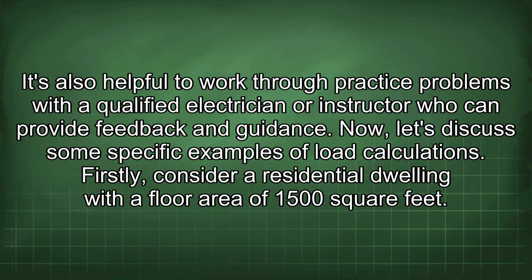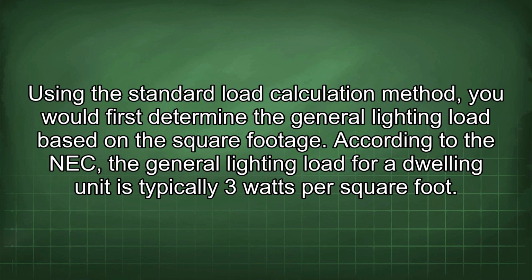Now, let's discuss some specific examples of load calculations. Firstly, consider a residential dwelling with a floor area of 1,500 square feet. Using the standard load calculation method, you would first determine the general lighting load based on the square footage.